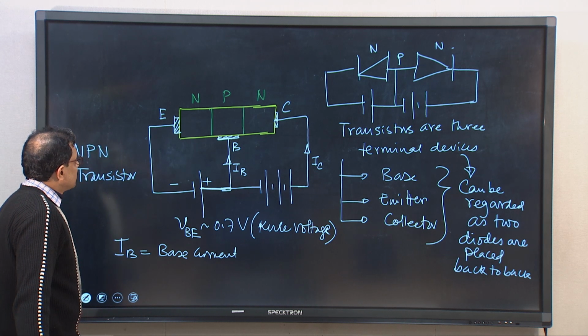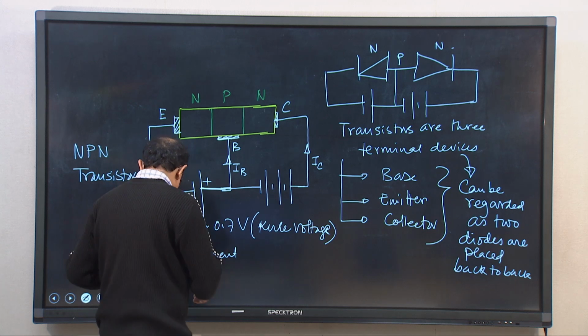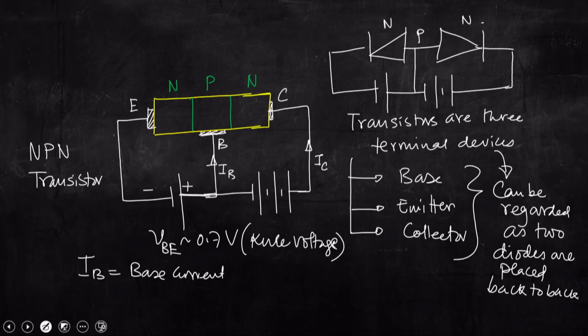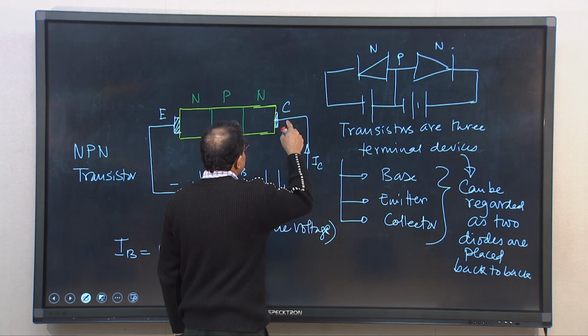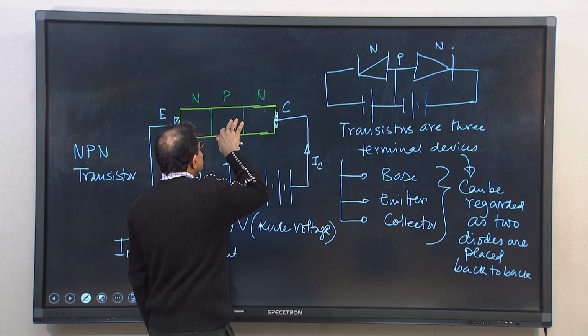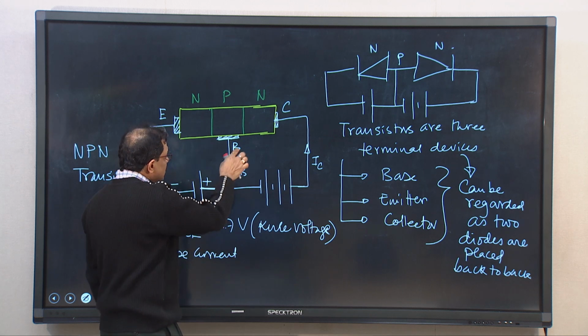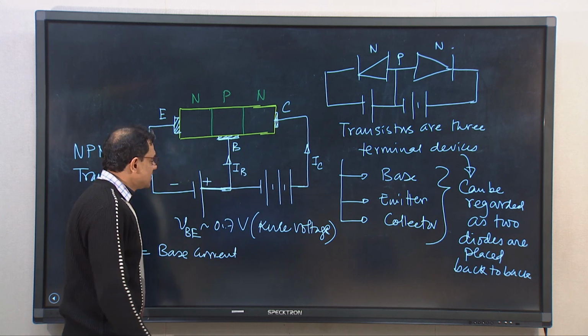That is the concept. Now, what we can see from this particular circuit is that under normal operating condition, current flows forward from the base to the emitter, but does not flow in the reverse direction. So current cannot flow from negative to positive. Under normal condition, from base to emitter, a small current will flow if the voltage is 0.7 volt or more. Only when the small gap, the small opening area, is there, that is the moment we break the barrier, a significant amount of collector current will flow from collector to emitter, because the other way it is not possible, because this will be negative with respect to collector, right.